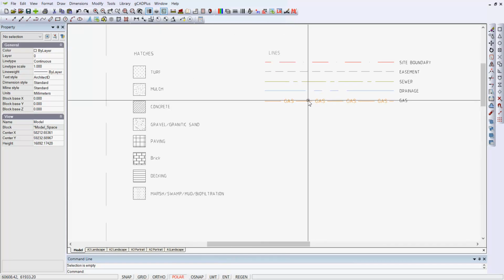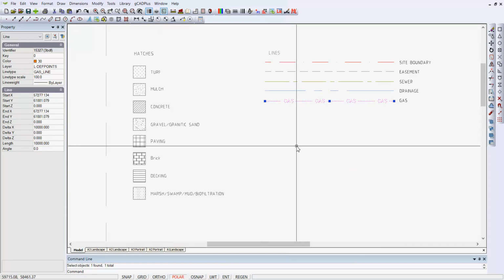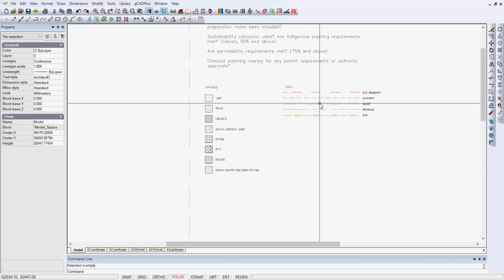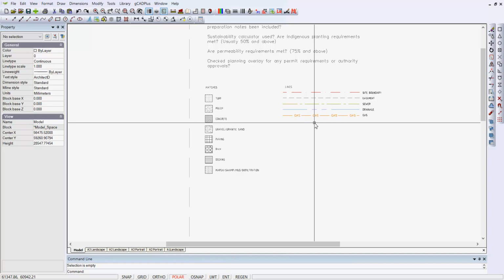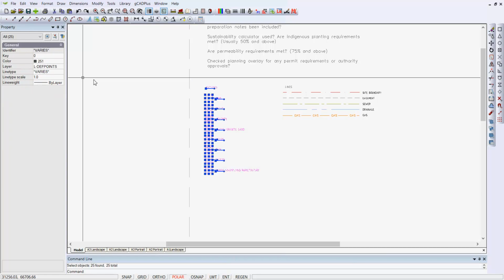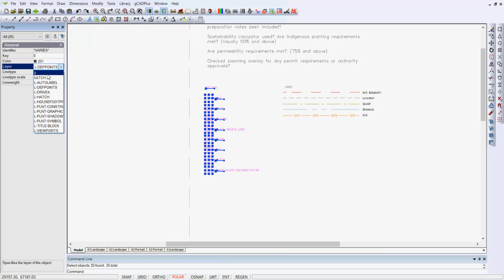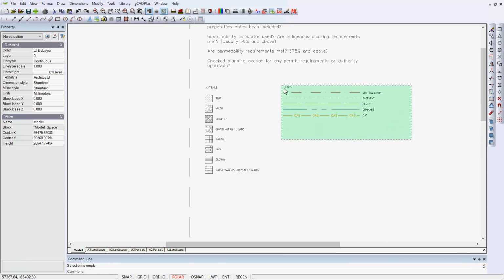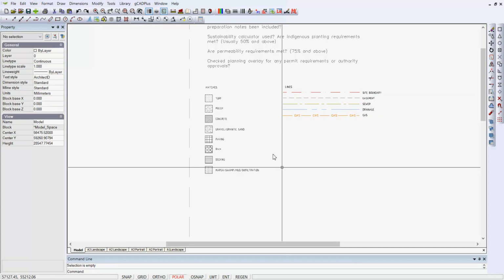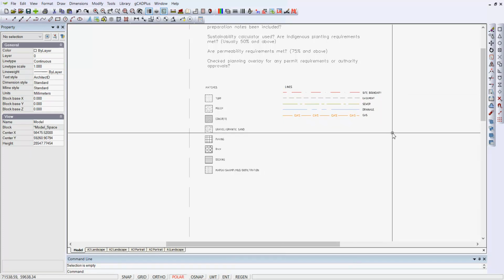Even the little different line types here are also on that layer, so that if during the development of this design we wanted to use some of these line types, we'd have to bring them from the non-printing layer to the working layer, and the working layer here is layer 0. So if I wanted to use these hatch patterns that are here, I grab all of those and change them from the def points layer back onto layer 0, and I might well do the same here, grab all of those and pick 0. The way I'm grabbing those is what's called a crossing window.